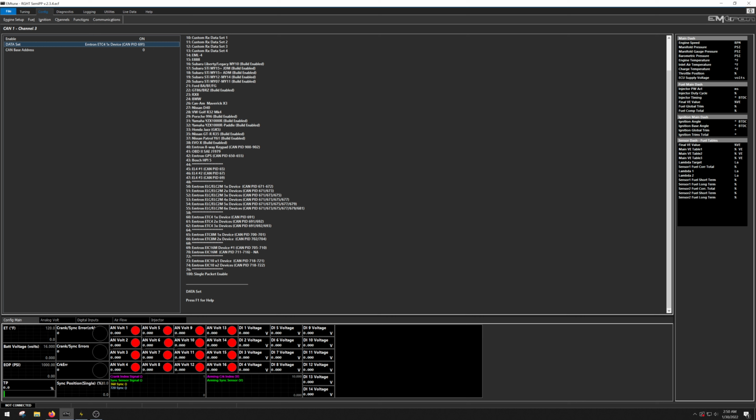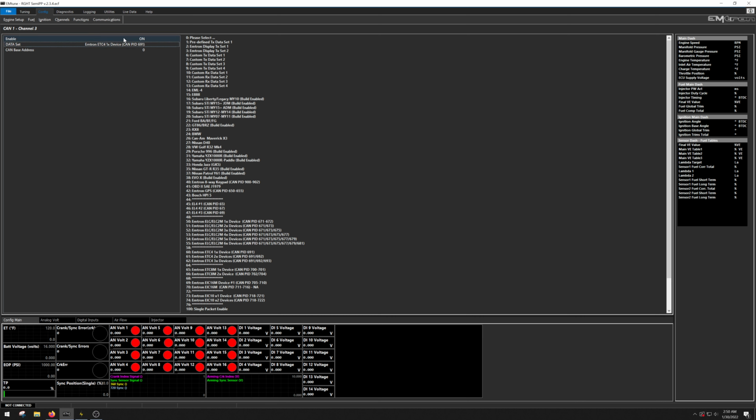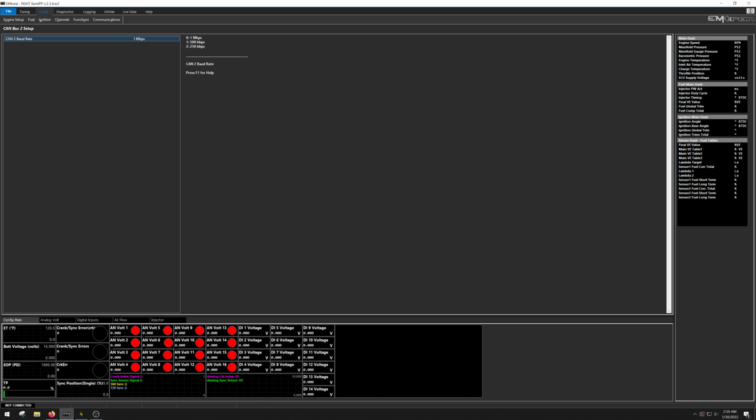And that's all of this ECU is going to have to export on CAN 1. CAN 2, I'll probably have display stuff, which will be, I'll have to see if the speed needs to be 500 kilobits per second. And if I want to do this